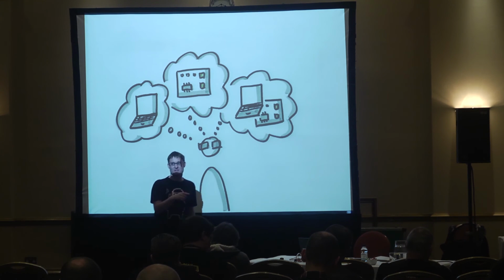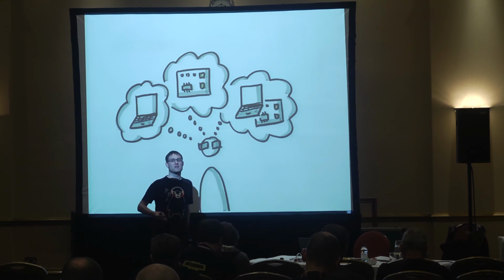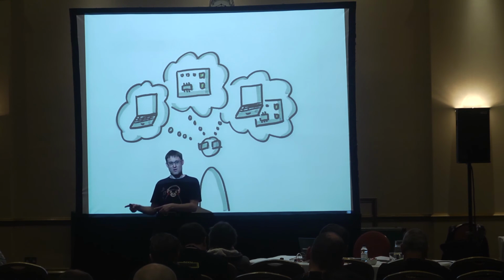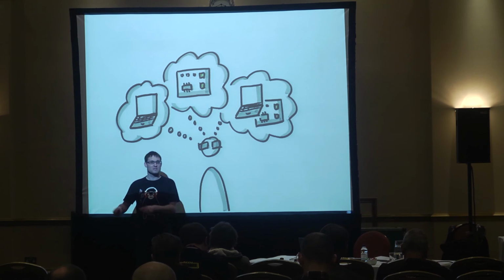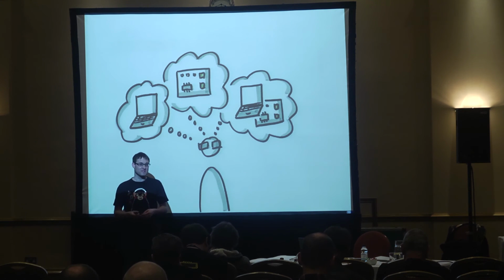And also, if you can, you should try to automate that in the continuous integration system. Because if you have a good cycle where you can develop separated from the hardware, there is also the danger that you're going to break something only on the target, and if you don't have automated tests in your continuous integration system, it's easy to miss them. Then they only come up maybe after 2 weeks, when you look a little bit at the hardware, and you discover it has been broken for 2 weeks.